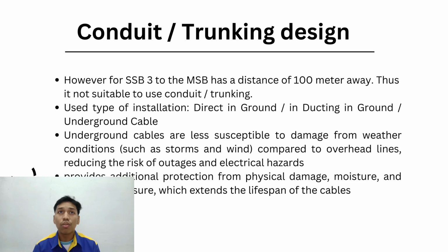So why do we consider using this? It is because underground cables are less susceptible to damage from weather conditions such as storm and wind. Compared to overhead lines, it reduces the risk of outages and electrical hazards. It will also provide additional protection from physical damage, moisture, and chemical exposure, and extend the lifespan of the